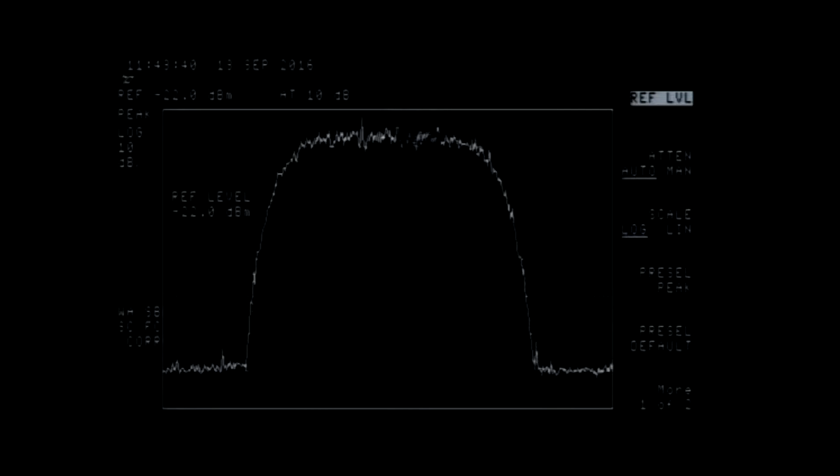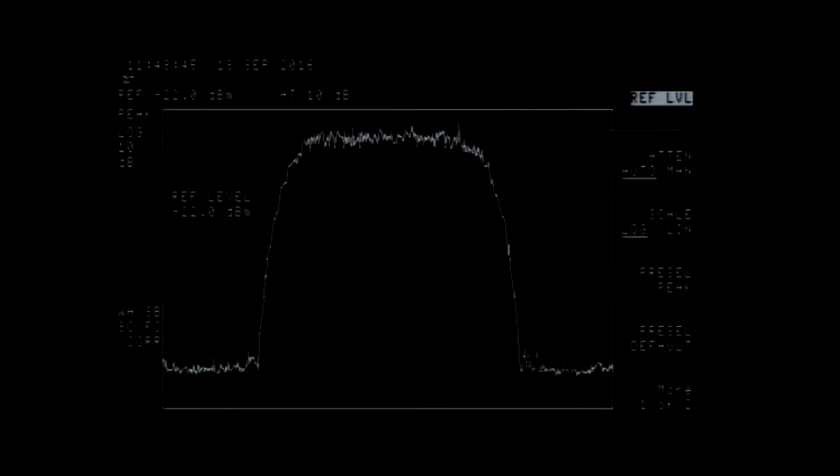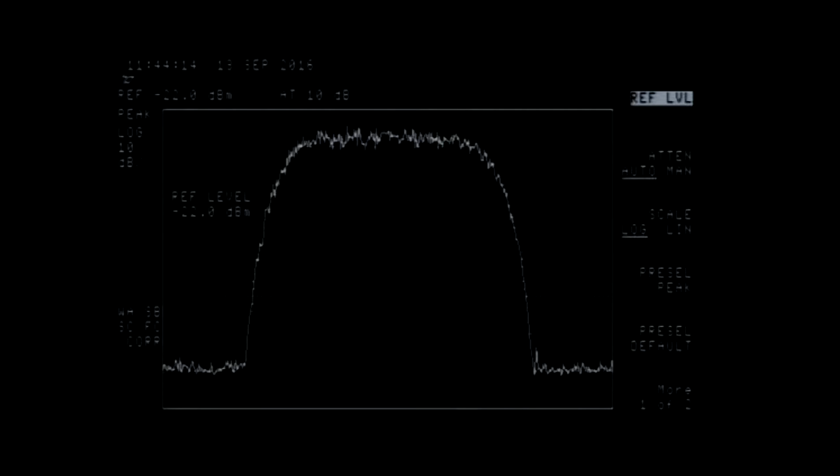If I now go to a 0.2 roll-off, now you can see a narrowing of the signal. 0.25 is an intermediate between the two, which I won't bother with. But the change probably won't make much difference to us, but certainly on a wideband satellite link it would make a considerable difference. Back to 0.35. Watch now. There you go. That's it.